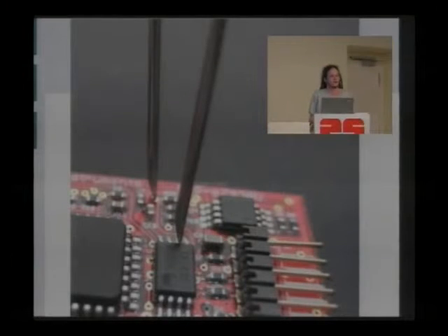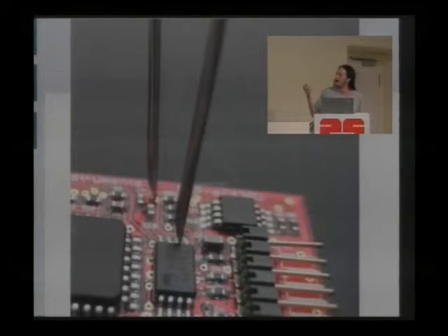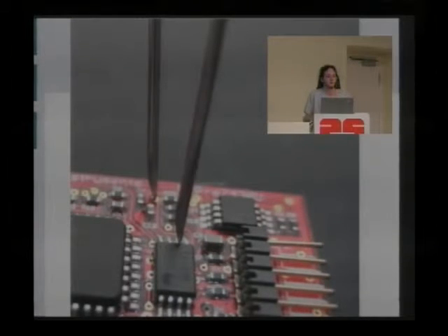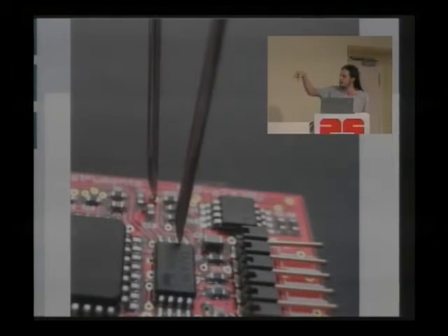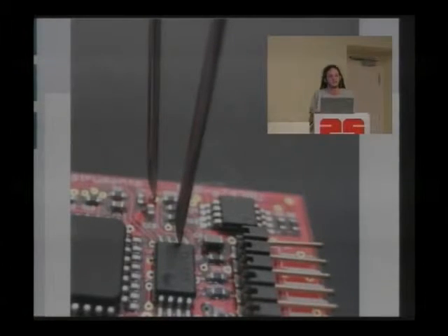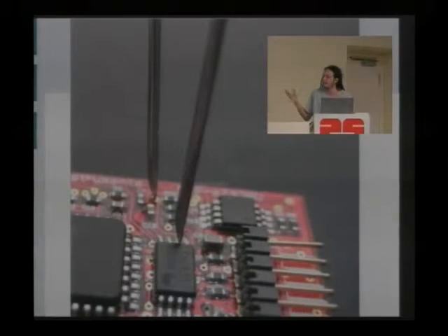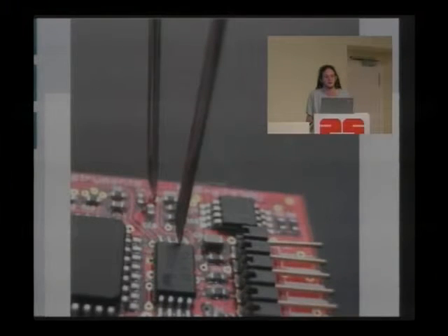So to dump the code, I took 2 hypodermic syringes running to an I2C adapter. And the nice thing about I2C is that it's multi-master. So when I plug these syringes into the board, and I've got the board plugged into the USB port, I can actually dump the code of this chip on the same bus that's being used by the actual chip in operation, and there are no collisions, there are no errors. I get a clean dump of the chip, and the operating system doesn't throw any errors or complain.